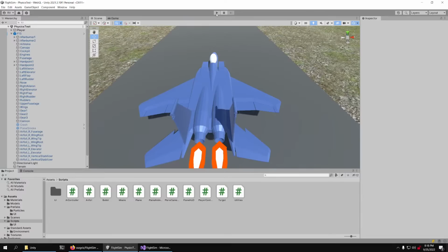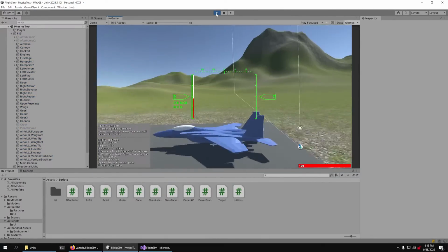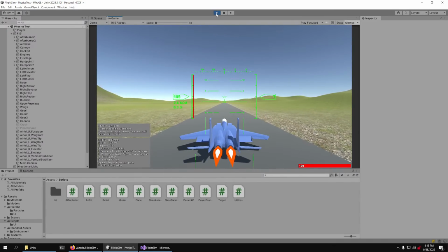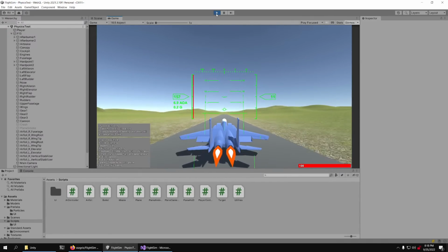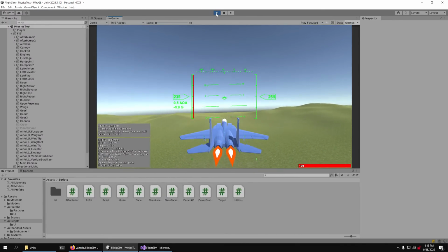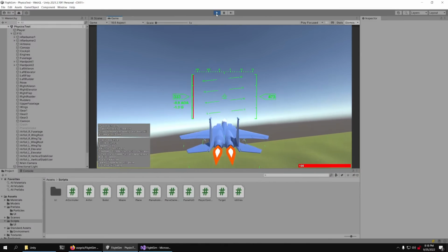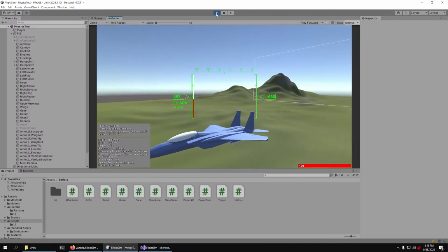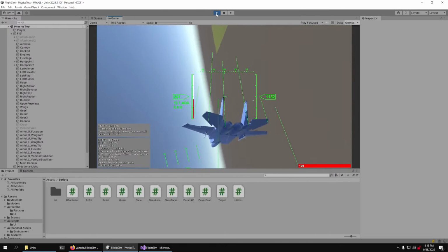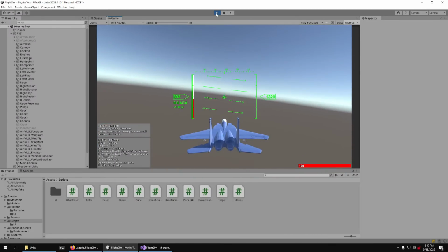Yeah, so this is a very complicated rabbit hole I'm going down right now. This is just not an easy way to fly the plane. It's much harder to control. What I've found so far is that the pitch axis in particular is really hard to control, because as a stabilizer, it's way too strong. It basically points the nose directly towards the velocity at all times, and there's a slow pitch down movement even when I'm not touching the controls. That is realistic because I haven't implemented stuff like elevator trim yet, but in general the pitch stabilization is really strong.